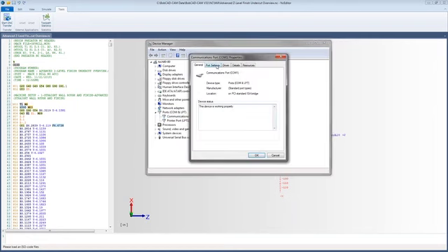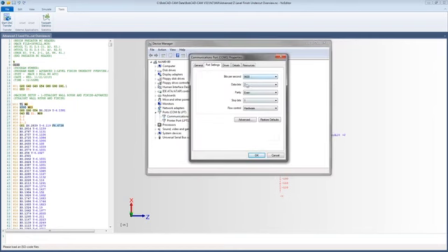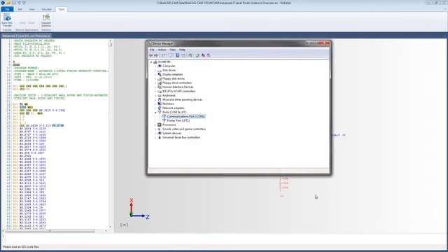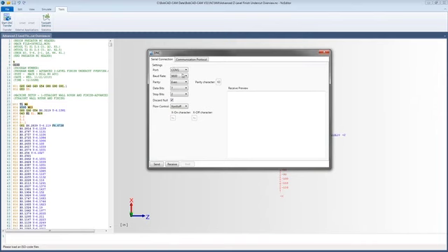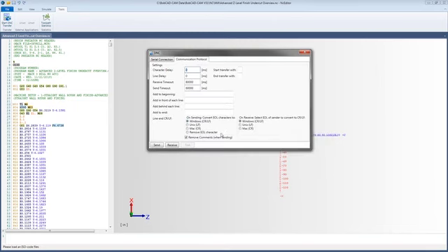If I go into the properties here and go to the port settings, there we have our baud rate, data bits, parity, stop bits, and flow control. If I go back over to the NC editor, we have the COM port, the baud rate, parity, data bits, stop bits, discard null, and then the flow control right there. And then right here you have your communication protocols. So this is going to give you delays in your characters or delays with your line delays. This is going to be kind of a drip feed. So you're going to slow down how fast you're shooting this code out to the machine and be able to bring it in. Like I said, if you are still using an RS-232, get in touch with me.